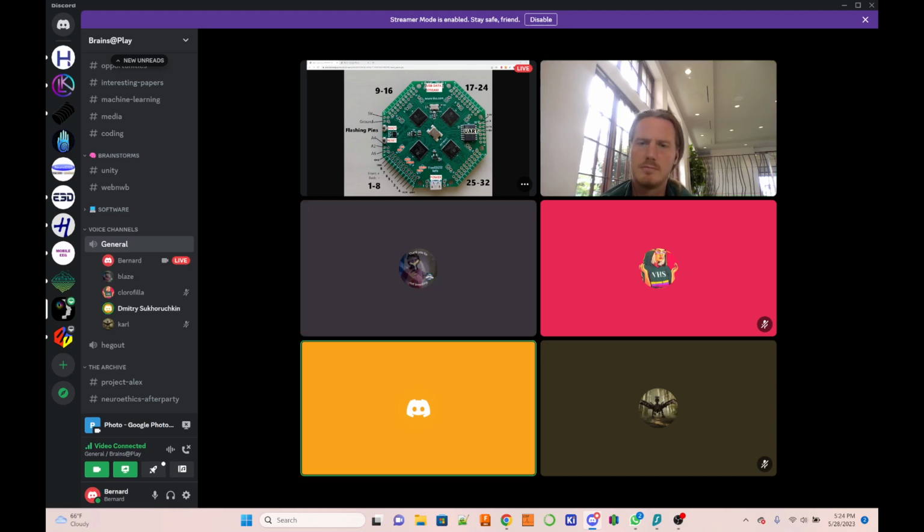It can be removed, this 5 and that 3 volts. Maybe it's not a good idea to wire them out. Better to power it anyway via the isolator and connect from the debugger only ground and the other 3 debug pins. As on all other dev boards, you're not connecting power when you're debugging. You only connect ground and something from the debugger. Power is always better provided from the output of the isolator, from the transformer.